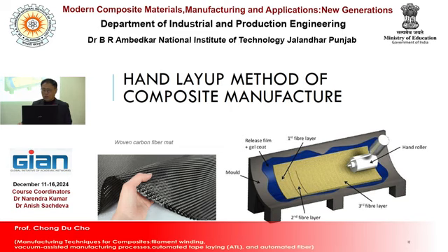The resin film and the gel coat are applied, and so you stack the carbon fiber mat in this case, or in other cases glass mat, any kind of mat prepared is stacked as desired. Okay? And after stacking, by using a hand roller, you apply the pressure evenly along the surface of the stacked mat.